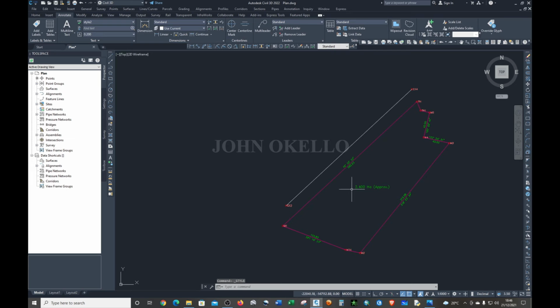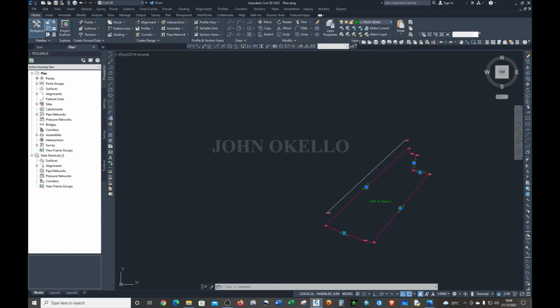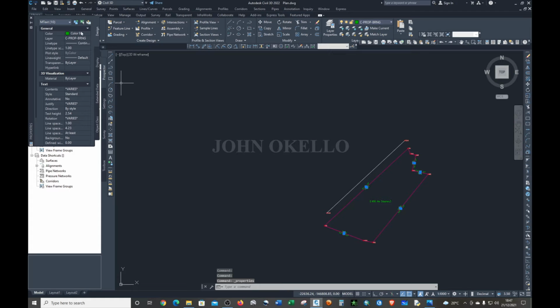Okay, so close. So if I select similar, we want our segment label to have Times New Roman text format. Under properties, first of all, we're going to change the color to white, and the font style, we're going to choose the style 1 that we set previously. Choose that, and click escape.